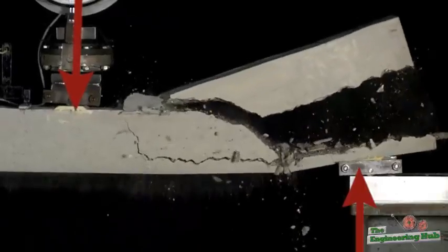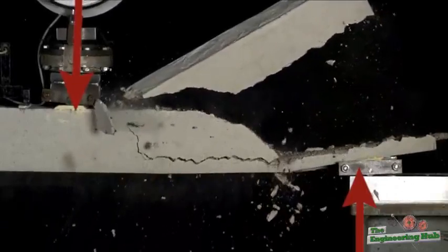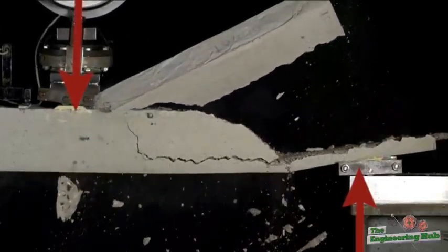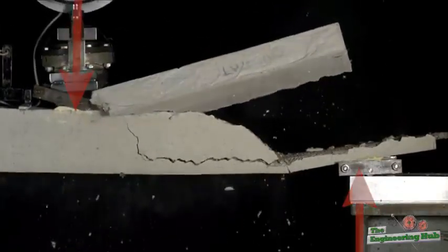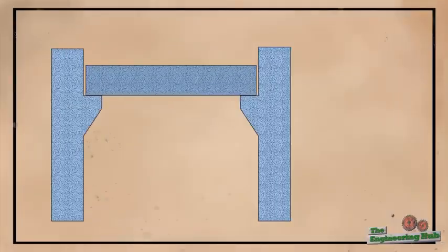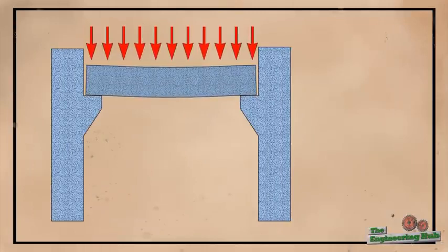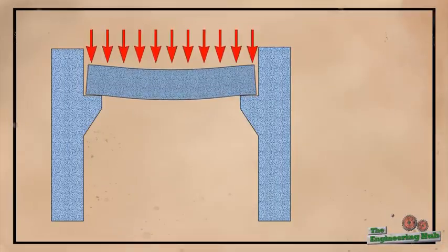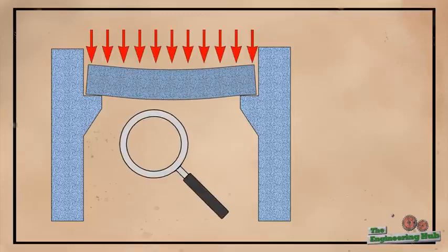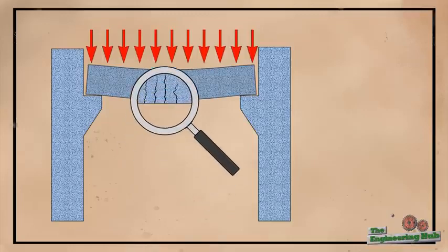Concrete is strong in resisting compression forces, which makes it ideal for columns or walls. However, concrete is incredibly weak in resisting tension forces. In fact, in design, engineers generally assume tension strength to be zero. This is because in structural analysis and design, concrete is assumed to be cracked, which prevents transferring of tensile forces.